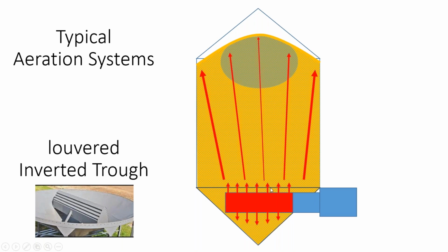So now potentially you can have half your air taking an easy path and only half having to travel the long tortuous path out of the bin. So you can see how this will impact your efficiency and will reduce back pressure. The drying front is unchanged. You will accumulate moisture at the top of your bin, and you will have to move and blend your grain for winter storage.